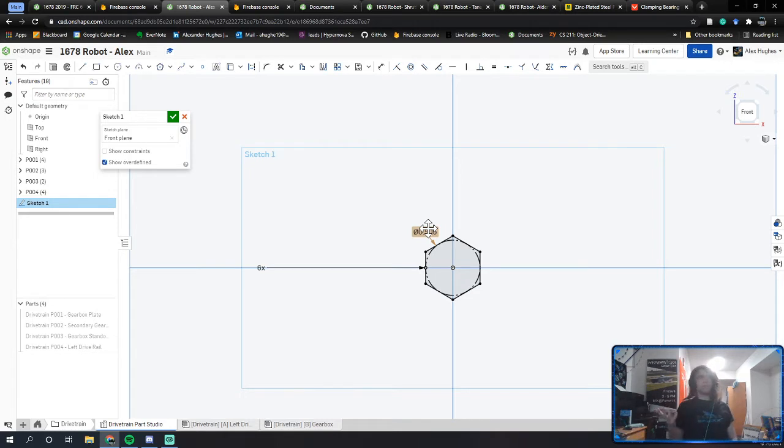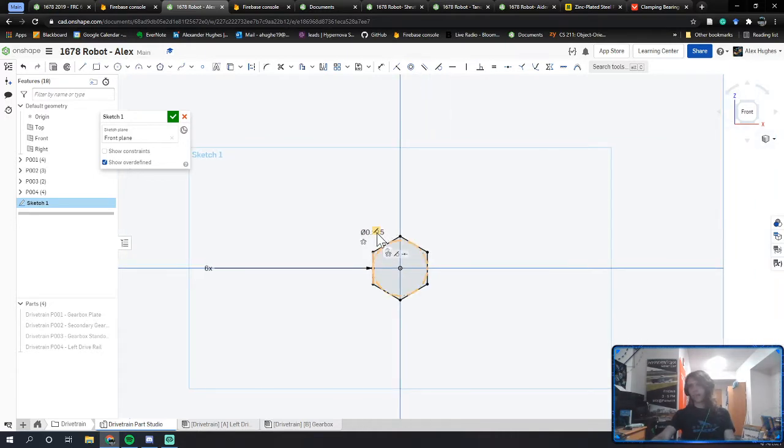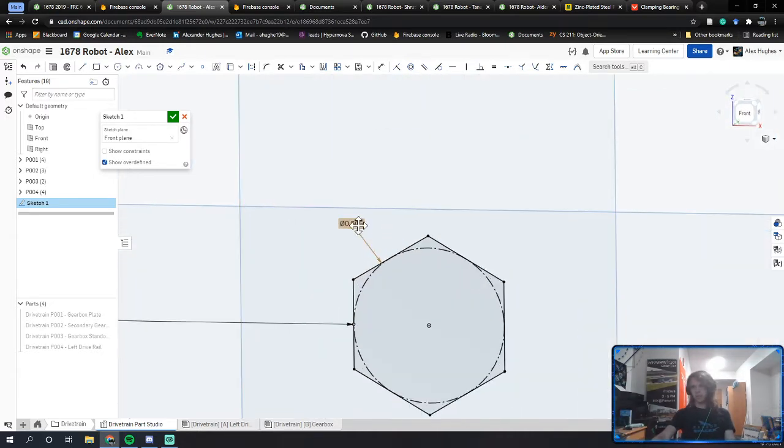Typically, depending on the 3D printer, and the 3D printers that we use over at the Build Space, we don't tune them perfectly. They're not like my 3D printers where I make sure they're good within 1/1000th of an inch or whatever. I typically add about 5/1000ths of an inch. So I set the inner diameter to 0.505, just so I know they will slide on nice and easy.